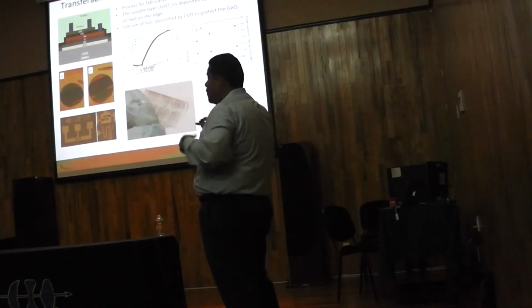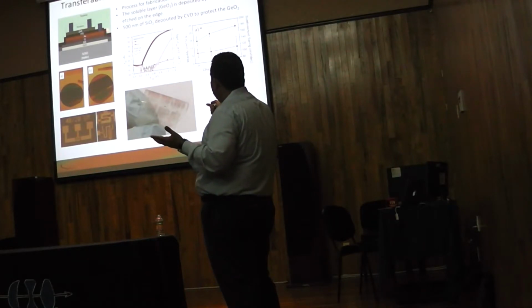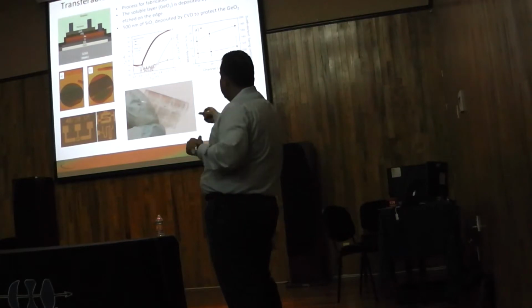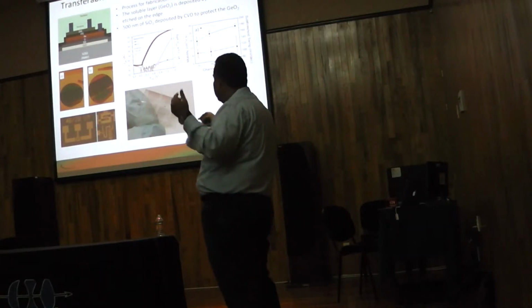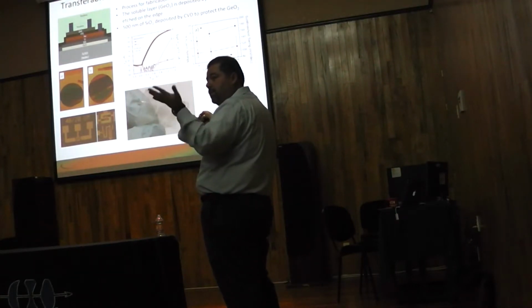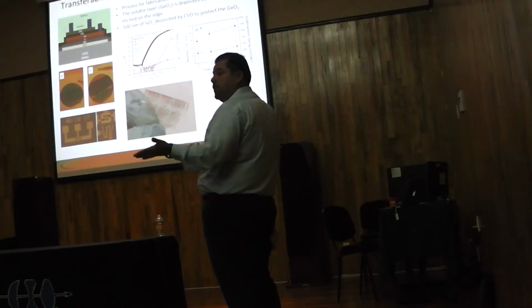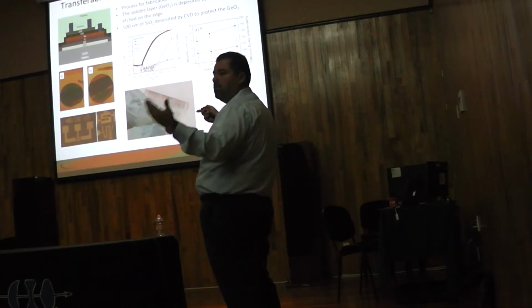We do the process. Once we finish the processing, we open holes here and then put it in water. The water goes in and dissolves the germanium, and then our flexible substrate, or the devices, float in the water, already covered by a parylene layer. So what we have now is we simply rotate this. This is very thick, so I don't really need to transfer to another substrate.